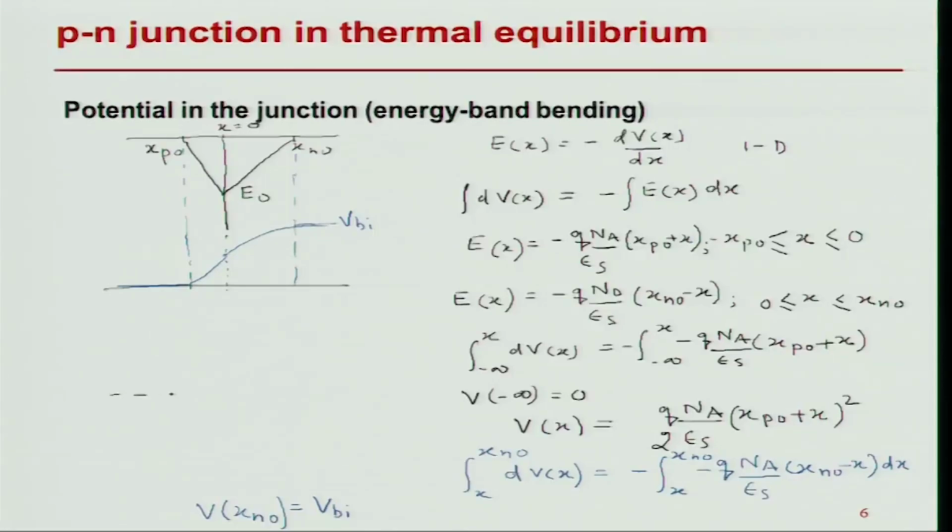In equilibrium, what I knew was that I have a Fermi level which is the same in both directions. Here, away from the junction, I have what is there in the material. In the junction now, what will happen? Built-in potential is increasing, right. Now, this potential is plotted with respect to a positive charge, and I am plotting the energy band diagram always with respect to the electron energy.